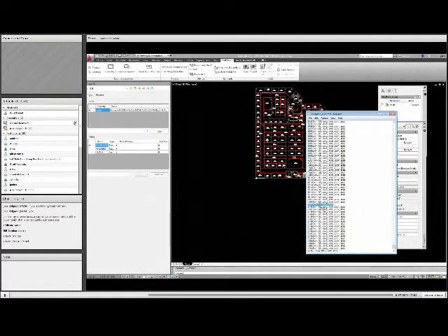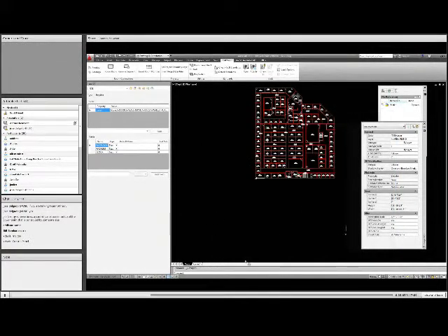By naming this esri_cad.wld, this will be the automatic world file that's used for all CAD files in that folder. If you only want this to do it for a single CAD file, you want to name it the same thing as your CAD drawing, but .wld. So go ahead and save that. And once I have that, I'll bring open the campus editing template that Esri has, and we'll bring in that floor plan real quick.